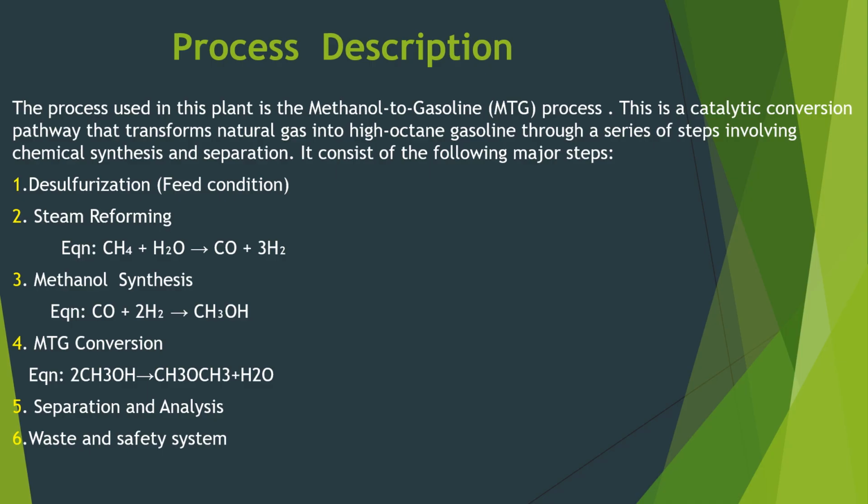5. Separation and analysis. The reactor output is condensed and separated into gas and liquid phases. Gas samples are analyzed via microgas chromatography, that's micro GC, and liquid samples are analyzed using gas chromatography mass spectrometry, that's GC/MS. 6. Waste and safety system.